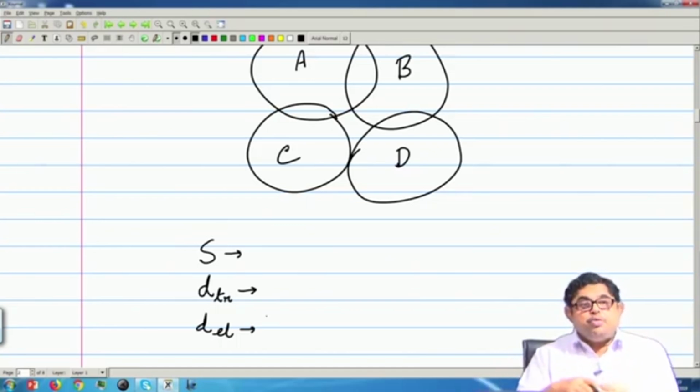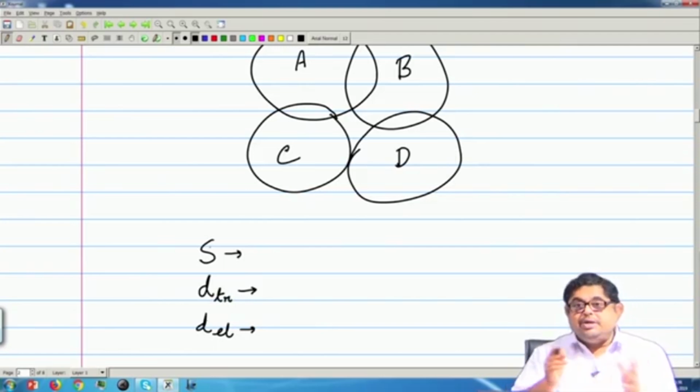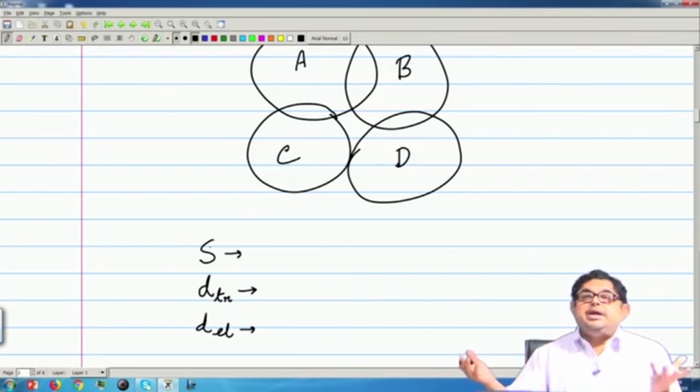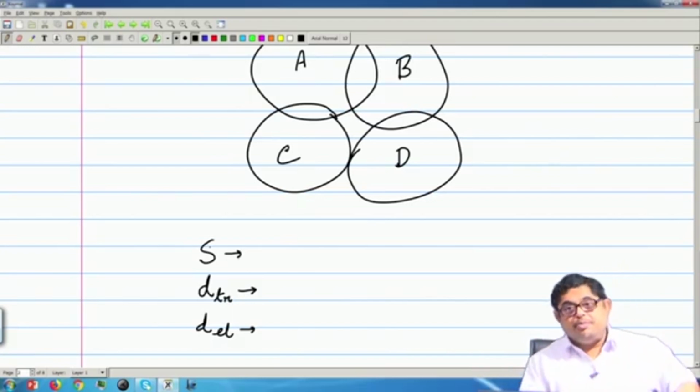We will later prove that point. So, even if the receiver's reference oscillator drifts, there is no problem. All the values, this dTr, d elevation, S, will change, because drift will make those complex voltages or patterns change, but the ratio is invariant to drift. So, that is the beauty, that is why it becomes so precise.